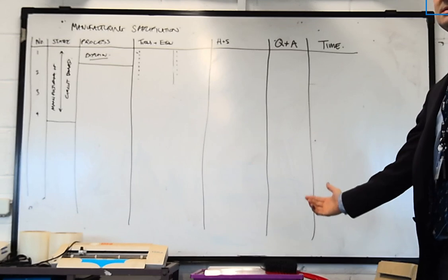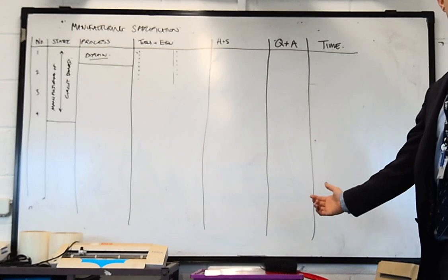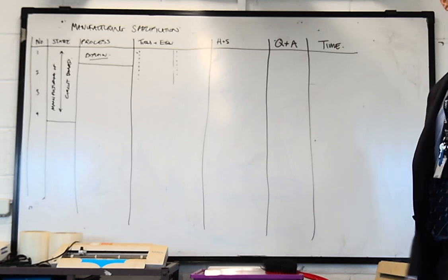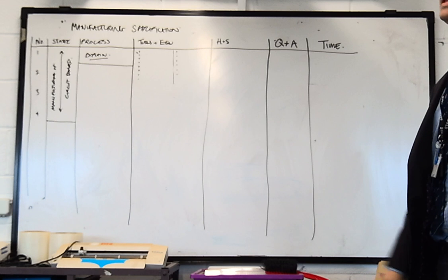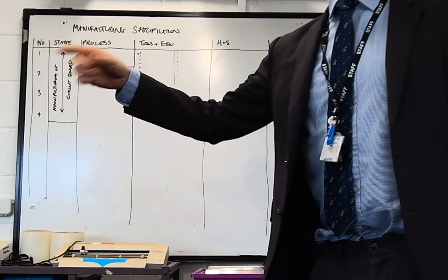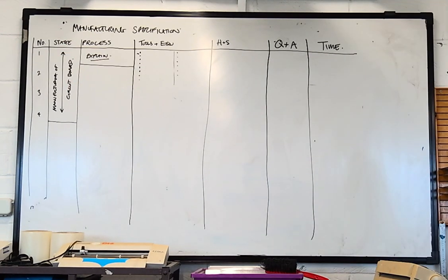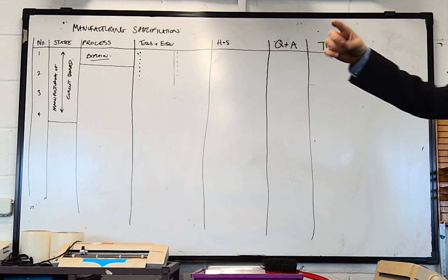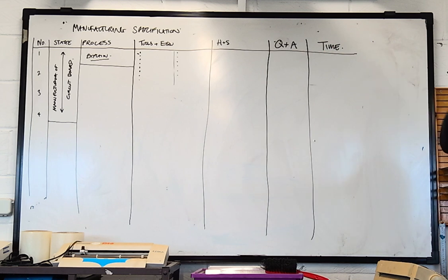Any questions? No? So it would be PCB, and then the next thing is going to be developing, isn't it? Developing might be a stage in itself. It's quite a complex stage. After that, then we've got the etching. After the etching, we're probably going to take it out. I would then probably have the cleaning with wire wool and drilling as one stage, because they're quite similar.